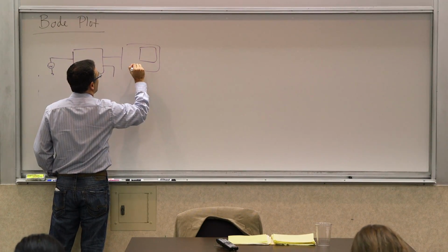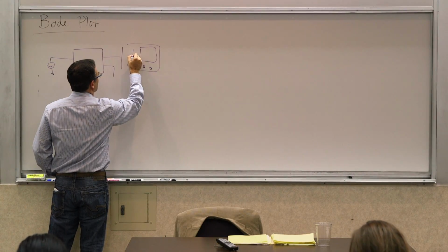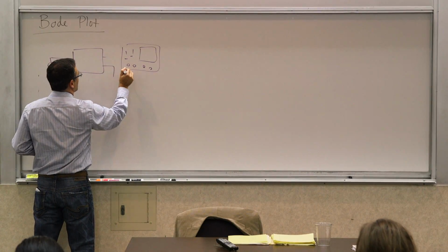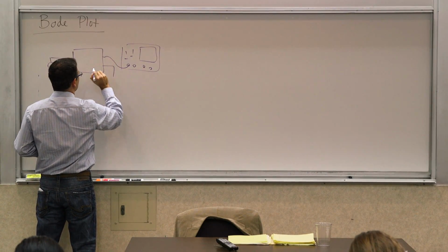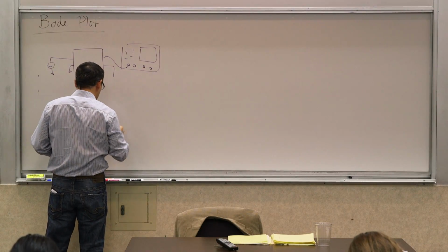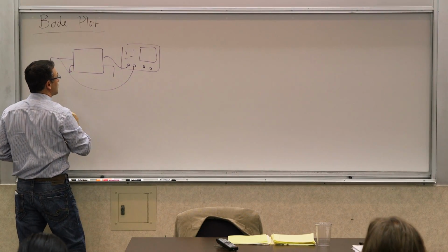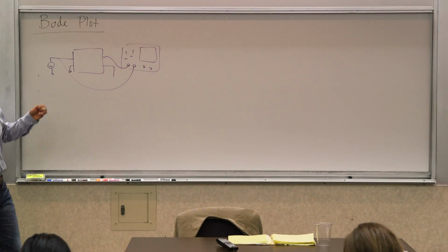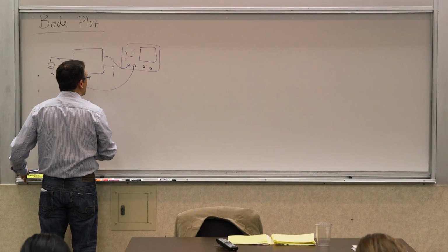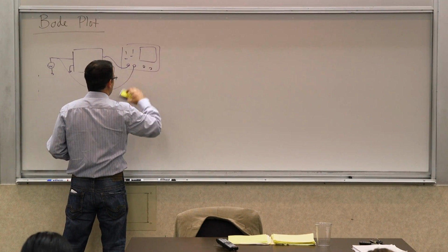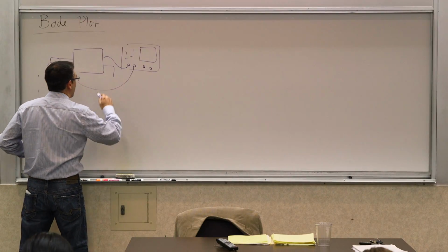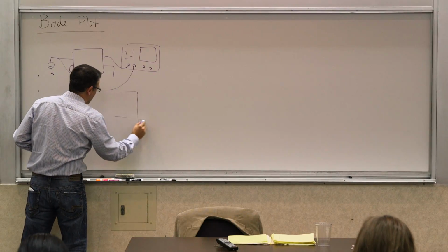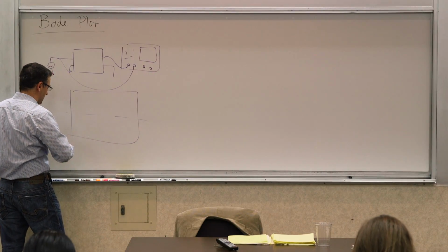So this is the oscilloscope, and it has its knobs and controls and things of that sort. And what you do is you take a probe from the oscilloscope, and then you look at the output here, and then you take another probe and connect it here, so you see both the input and output at the same time on channel 1 and channel 2, for example, from a very practical standpoint. And when you look at the screen of this oscilloscope, so let's say if I magnify the screen of this oscilloscope and put it here, what you really see is that you will see two sinusoids.